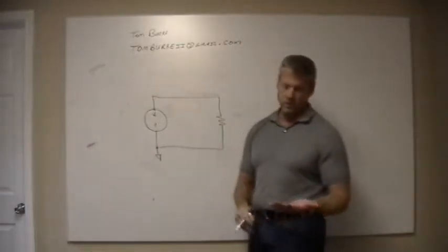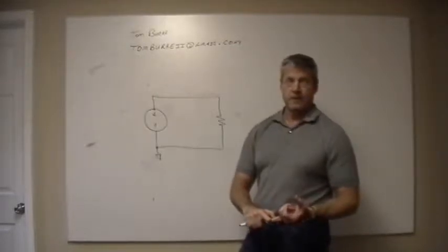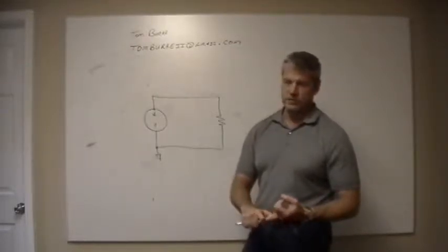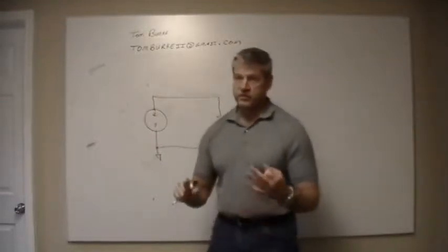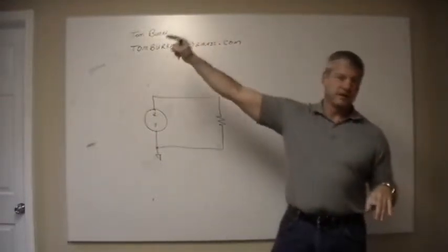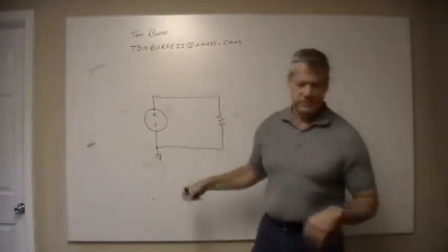If you crack open your wall, you'll see a black wire. Black's your hot wire, I think, white's your neutral wire, and green is your ground. The truth is, ground and neutral are usually tied together back in the fuse box, but ground is the one that goes out to cases and protects you. It's a safety ground.